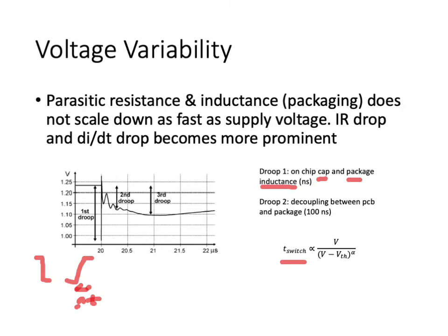And so any large changes in voltage, so from L di/dt, okay, this is the inductive changes, will lead to huge swings in voltage. And what happens is these large swings in inductive and resistive parasitic voltage drops cause a significant droop in the voltage supply to transistors. And of course, if you've studied the noise margin of digital logic gates, if the voltage headroom drops below a certain amount, then this introduces noise and may actually cause trouble, a corruption of the digital values.